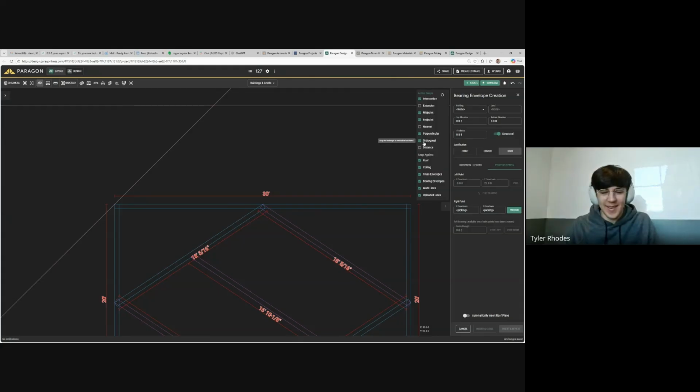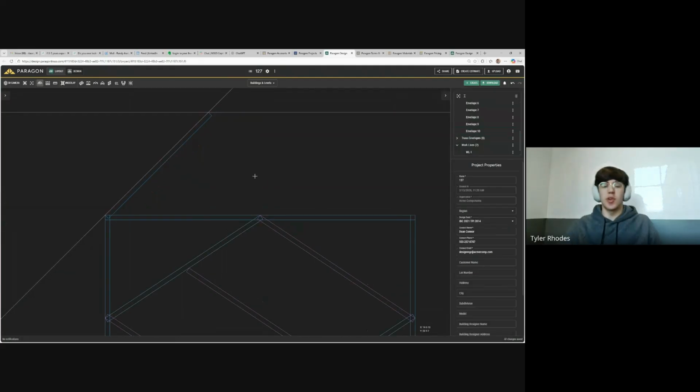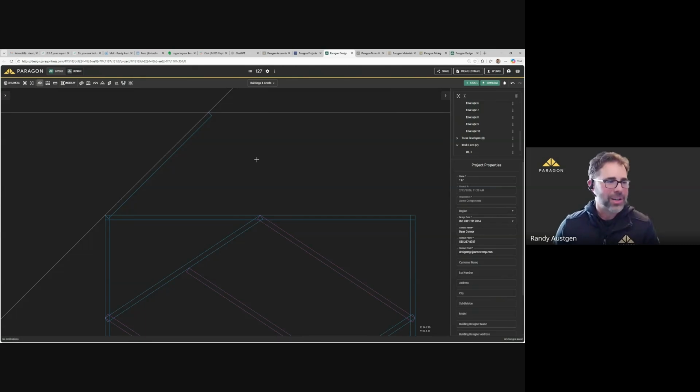Well, now that as you were explaining it, I thought of something. So if you're doing a 45-degree, something simple like that, I guess you could just put in 2 temporary walls. So say the offset for the 45 is like 5 feet. So you could just do 5 foot over, 5 foot up, and then do some temporary walls if you didn't want to go into the work lines. But yeah, a lot of times on the architectural plans, especially for those like the bay windows, it will give you the X and Y coordinate. So for a bay window, for example, I might even come up here.